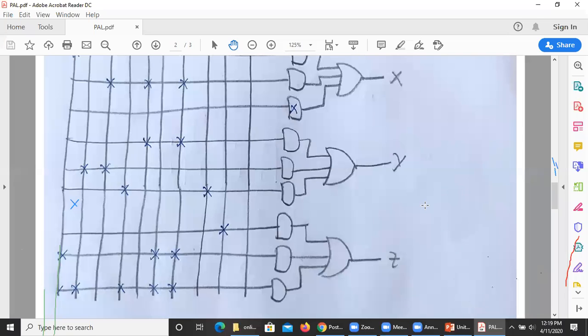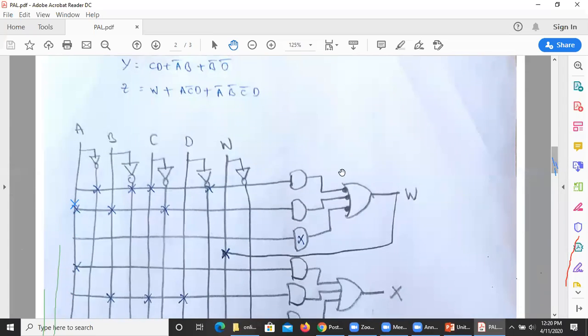But the inbuilt PAL contains one or two terms which take this input and also output. That's why that feasibility is there in PAL. So due to that we are taking it like that. Okay. So if you are not having this type of connection, then what happens? This output contains totally 4 product terms. So 4 product terms means you have to choose another type of PAL which contains 4 product terms in each output equation. So 4 product terms means automatically the number of product terms increases.